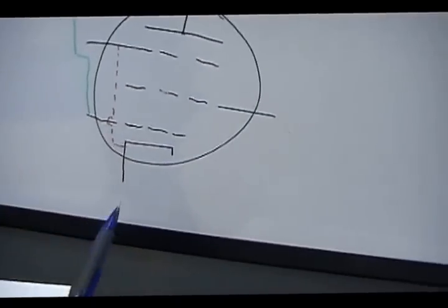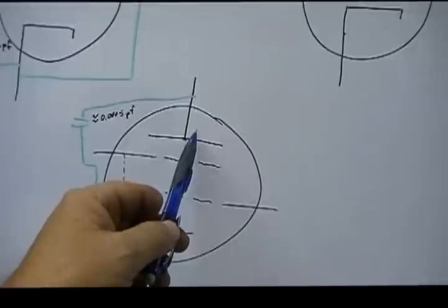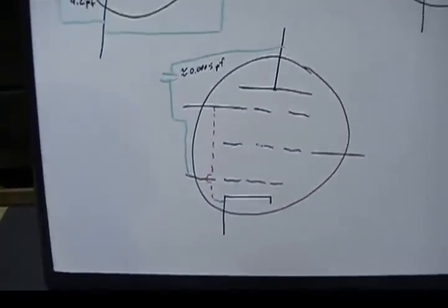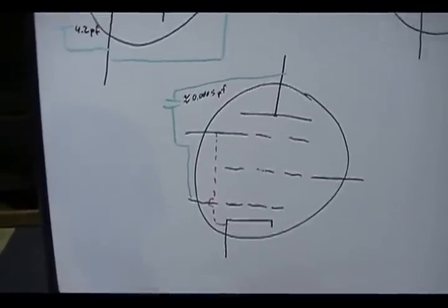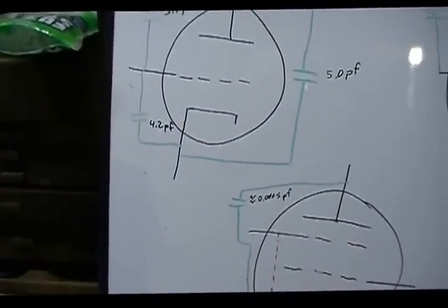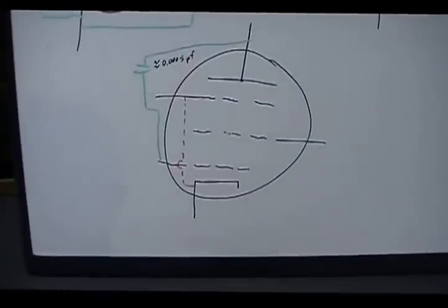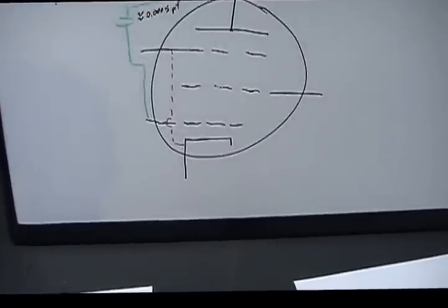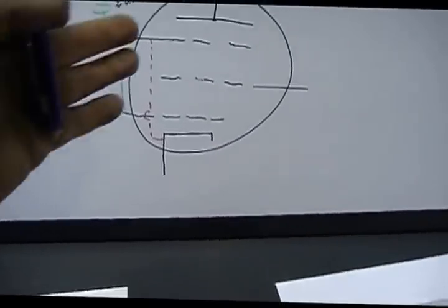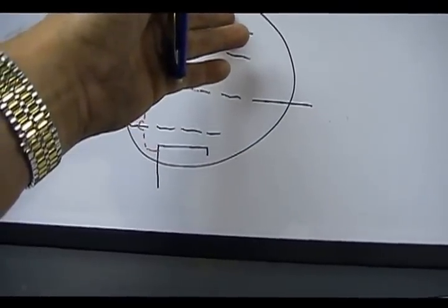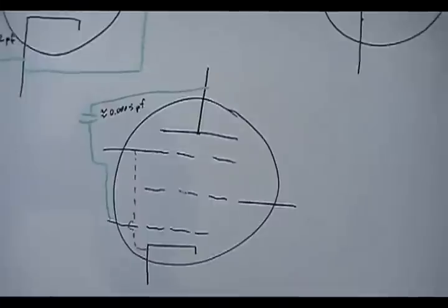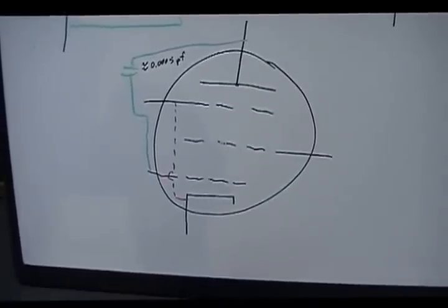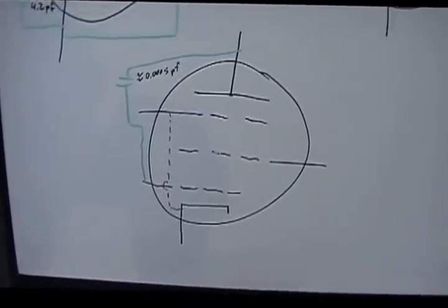So these fairly low transconductance, these plate resistances can be quite high. These can be well, in pentode tubes, well into megohms, 1 or 2 megohms of plate resistance, where a triode is more a few thousand ohms. But that goes into the power amplifier situation. That means that this impedance here is much higher, and that allows it to be a more effective power amplifier as far as power goes, and we'll get into that, talking about the difference between voltage amplifiers and power amplifiers.